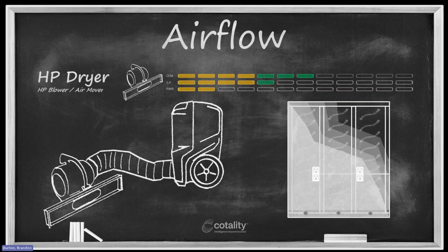And again, because there's electrical running through these cavities, or these are metal studs and there's lots of knockouts, I don't need to use the more complicated low CFM high static pressure blower. Your standard run-of-the-mill 1 horsepower blower with an attachment that lets me address 20, 30 linear feet of wall with a single turbo vent setup is going to give me significant wall coverage with extremely high rate of flow that is not going to be resisted based on that installation.